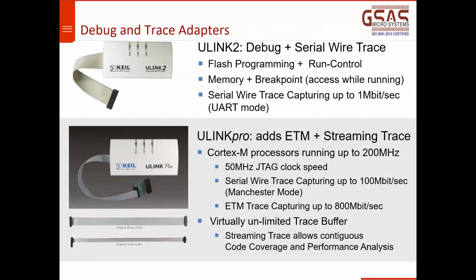Now let's quickly go through what adapters we have. I'll go through quickly because my colleague has to demonstrate the software, showing you the profiling application. So we have ULink2 and ULink Pro. ULink2 is a lower end debugger. It doesn't have any support for instruction trace, but it supports data trace and on-chip trace. ULink Pro supports data trace as well as instruction trace.